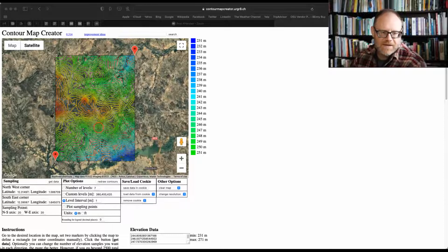If we're trying to understand the influence on that site, we again do what we did before, and we go right angle to contour. Basically what we're doing is coming up from this, finding that top point, up from this, finding that top point again, probably come all the way over here. This will flow off and out, off and out, off and out. My Canadian is showing. And then probably there, I probably wouldn't even include that. It's probably going to be right here. This is going to divide, and then we're going to get a bit of pickup. So that would be that micro watershed, the water that directly influences this.